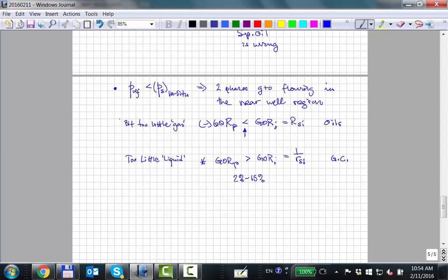So the point is that in both cases, the recombined well stream composition, when they put the two together in the producing GOR, may only approximate the in situ reservoir composition that we're looking for. That would be the in situ composition that you'd like, and the well stream composition is just not quite right because of the wrong gas oil ratio.